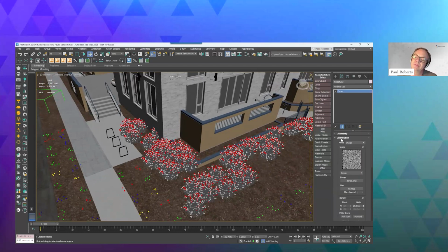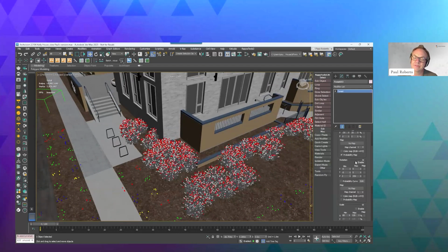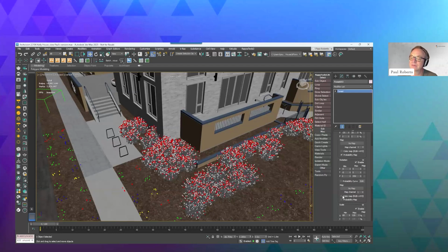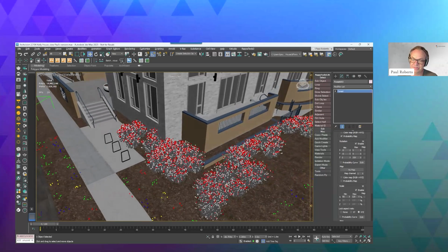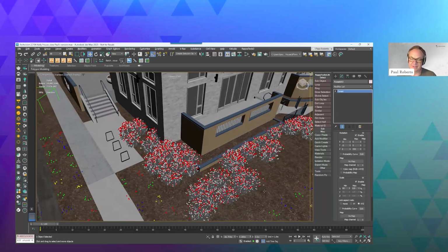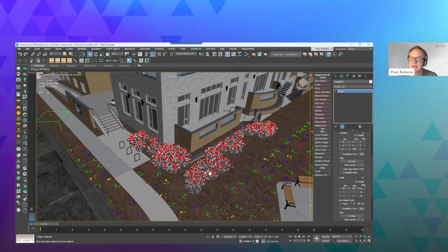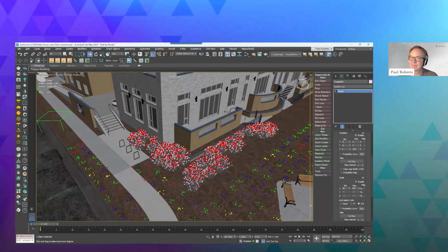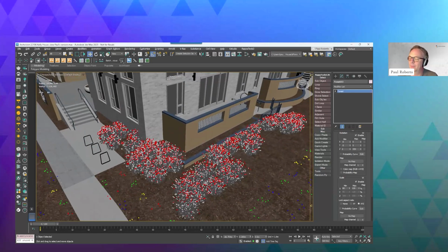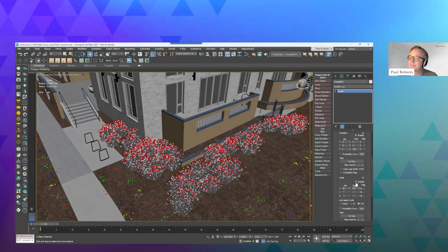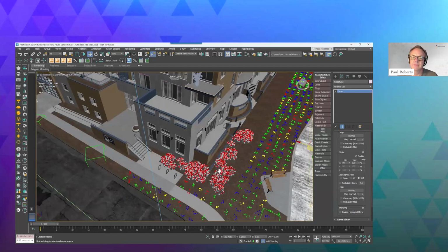So what we want to do is to look at the next rollout down here under surfaces, which is transform. And using that, you can randomize the rotation and the scale. And I'm just turning them on here. And that breaks up the repetition of those objects. Obviously, if you add a couple more variations to that, that pretty much disappears completely. I'm not rendering, by the way, just to save a little bit of time so we can just whip through. Okay. Makes sense, I hope.